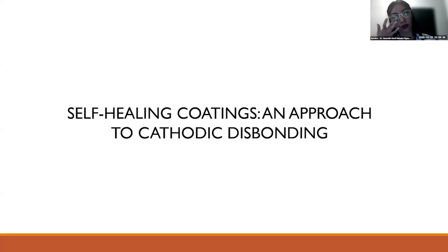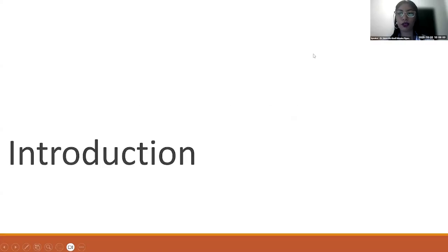Today I'm going to share part of my research regarding advanced protective coatings, in particular, how we can improve corrosion resistance in harsh environments using smart self-healing technologies. First, I'll walk you through the challenges of cathodic disbondment, how we address them by incorporating functional microcontainers into an epoxy coating, and the electrochemical results that we obtain.